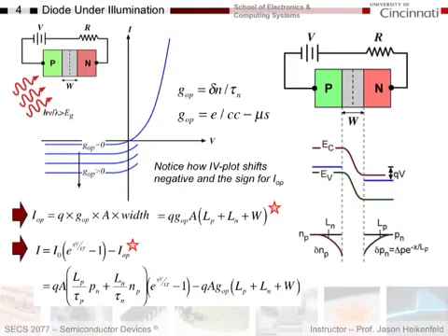So let's adopt our diode equation. It's not too difficult to do. What I want to do is take my optically generated current. I'm going to calculate it as Q to give me a coulomb, because I need coulombs per second. Optical generation rate, which is per unit cc per second. If I multiply that by cubic centimeters, then GOP over cc per second, times cubic centimeters will just give me 1 over seconds. 1 over seconds times Q will give me coulombs per second, which is current.